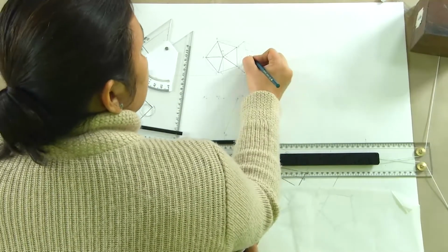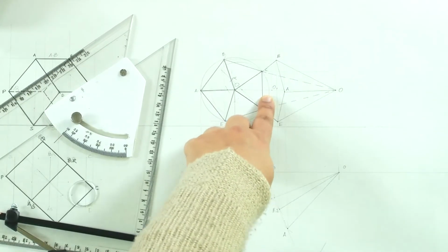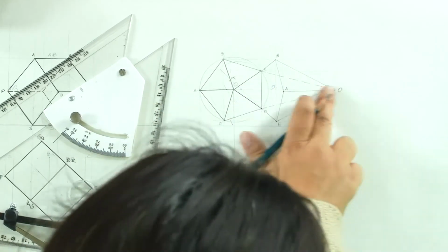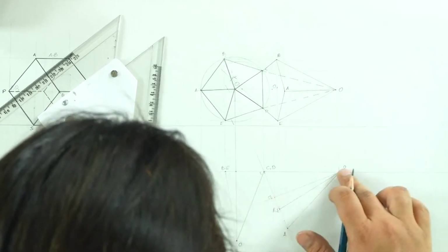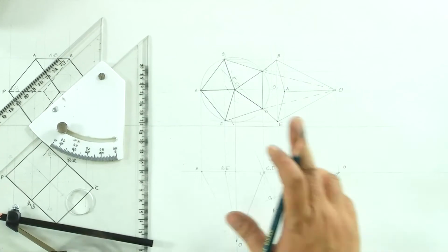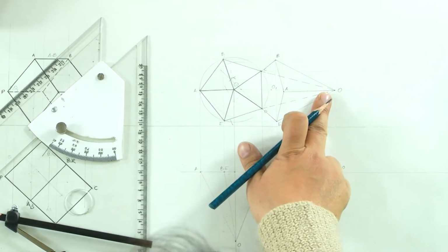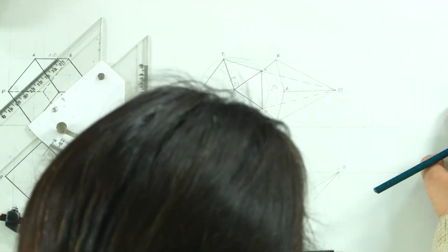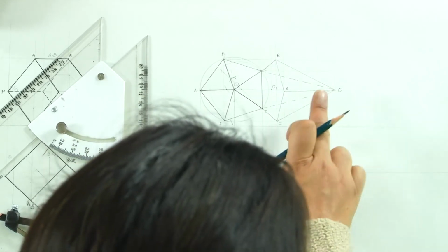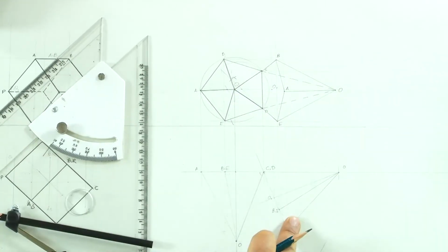So what we have here is A, B, C, D, E and O, and we also have an O1, which is the axis. Now if you see, this axis is still parallel to HP, but it is making a certain angle with VP, which is the angle of the cone. So the angle of cone is the angle which this is making, and so we see it slightly diminished here, but parallel to HP.